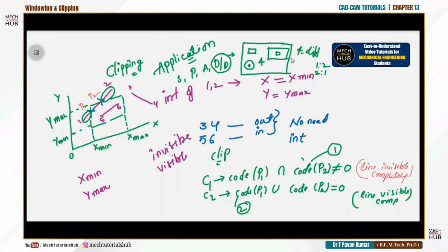All the scalings need to be followed in a single sheet, the draft sheet. To do so, viewports are very important. This viewport will help you. For example, in this window, in this portion, I'll place a viewport here. This acts as a viewport. Now in this viewport, I'll enlarge one entity by moving this hidden box front and back, top and down, right and left. I can place my image in this corner.